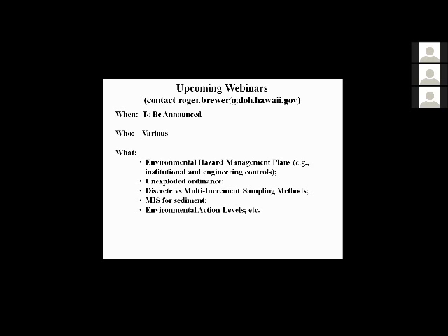Okay, thanks, Harry. Hey, Harry, this is Roger. I have one more question for you. Let's say I want to determine the mean concentration of a VOC within the middle third of a building slab. Can you install multiple passive samplers and then combine them in the analysis so I just get one analysis and just one number? I'm not really interested in the variability. I just want the mean.